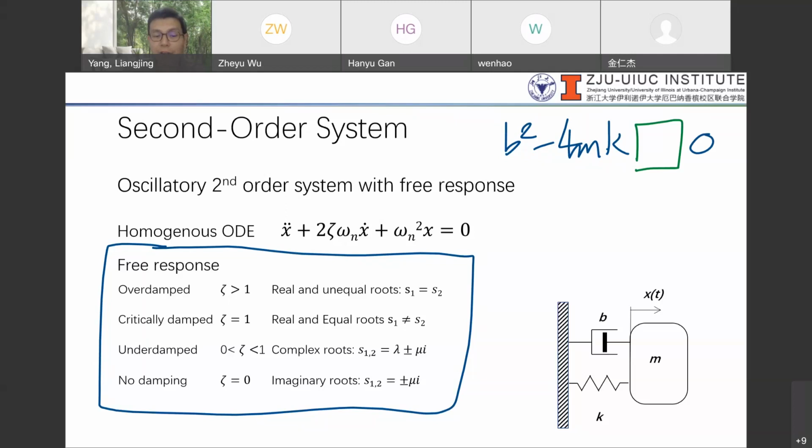When the damping ratio is greater than 1, it is over damped. Of course, just now when we were saying that it is equal to 1, it will be critically damped. Okay, so anything in between 0 to 1, it is under damped, right? When it is under damped, there will be oscillating, there will be a complex root, meaning your imaginary term will exist. So you're going to see something that is oscillating. When it is over damped, of course, it will just be exponentially decaying.